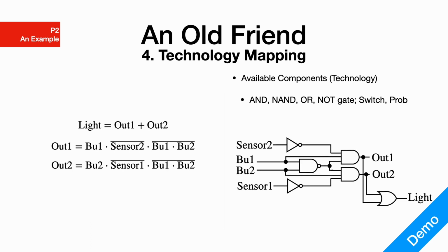Here we have used a NAND gate, 2 AND gates, 1 OR gate, and 2 NOT gates. On the left hand side, we have all of our inputs. Each of them you can use a binary switch in LogicWorks. We're going to show you how to do that in a separate tutorial video. And on the right hand side, you would use in LogicWorks binary probes for all of the output channels, 1 each.